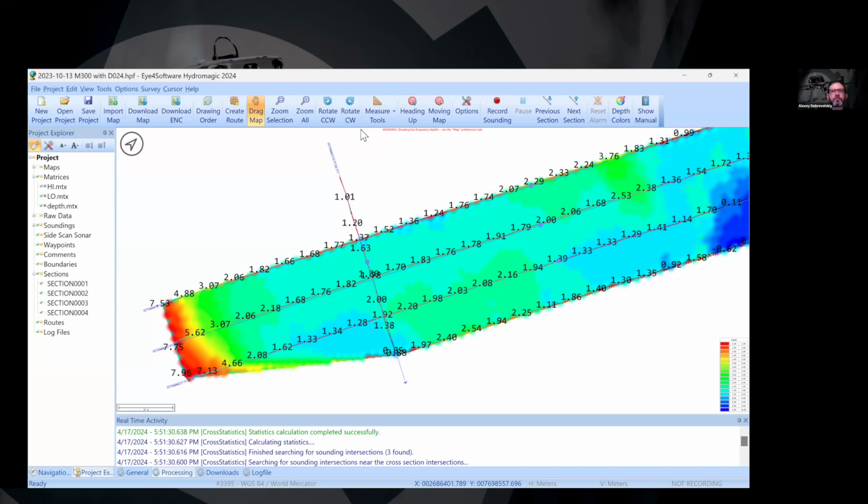Next question is, what about the radar profile measurement compared with the bathymetric measurement? I don't understand the question. You can use radar to measure the water level, but not to collect bathymetric data. Or if you mean low-frequency ground penetrating radar, I have data samples collected using low-frequency GPR and the echo sounder for almost the same cross sections.